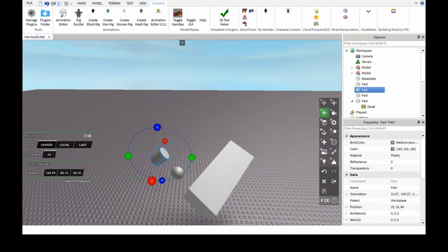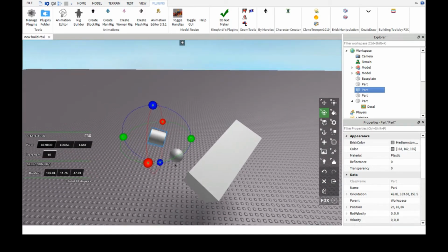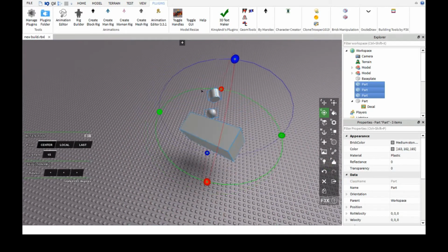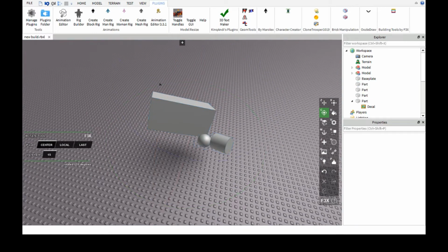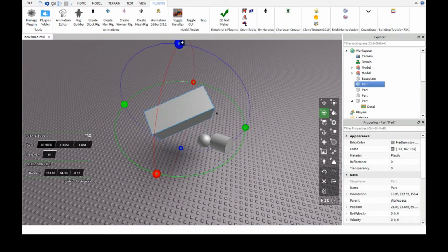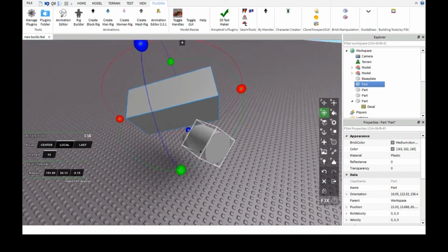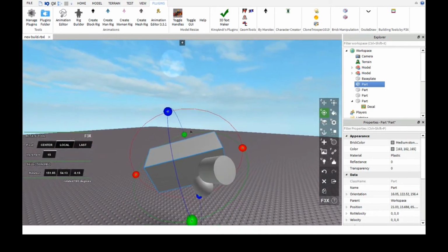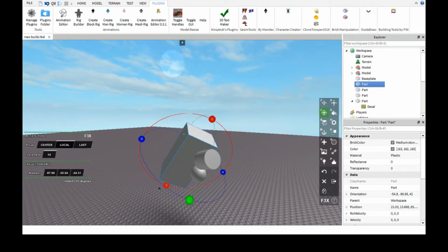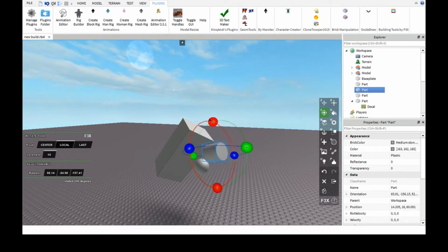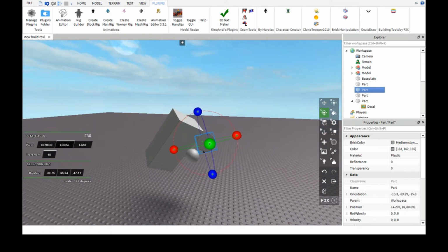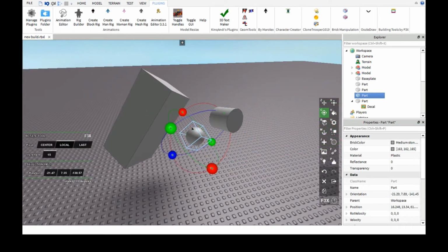And the reason for that is that over here in advanced options, I am on center. And what center is, it's the same thing as the global tool. They will all move on the same axis according to the map because this is on the global axis. This is on the central axis. And basically, I'm going to go ahead and click local and watch what happens. Just like the move tool, it goes to its central axis, its central pivot, and now it turns based on that. Each brick is different because it's rotated differently. Each brick will turn differently and have different options.